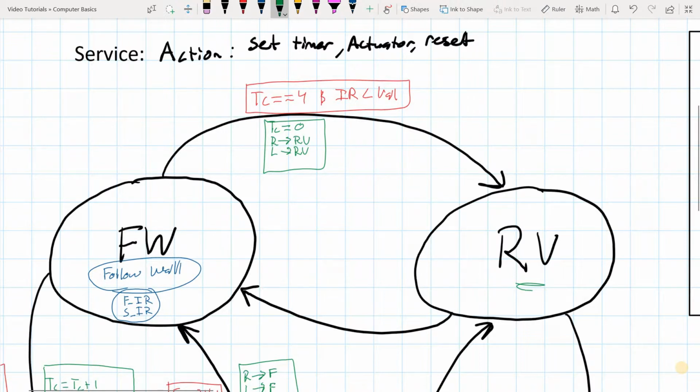But let's say you were rotating your industrial robot over to the conveyor belt, and the next state is to lower the arm. Well, then you would need to put in here, stop rotating, right? Because that's not going to be in the state lower the arm. There is no call to the rotational actuator in any way. So you would need to put it in here. So always write down your transitions here. Fill out your service. It doesn't take a lot to write this code, and it's good for you to be able to see in the transition from one state to another what exactly is happening.